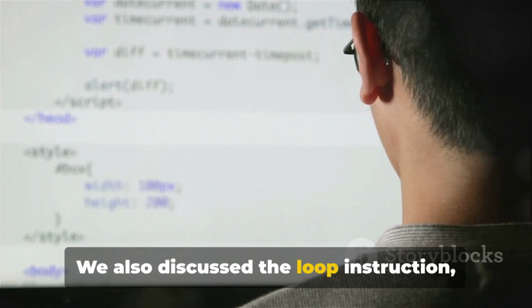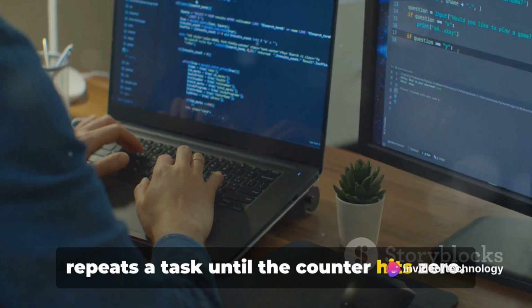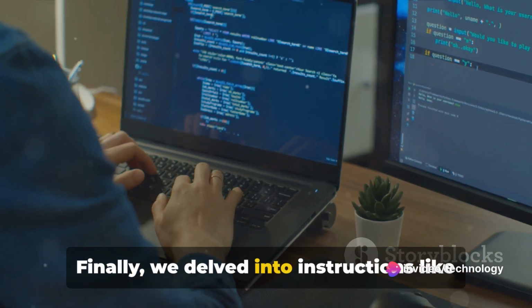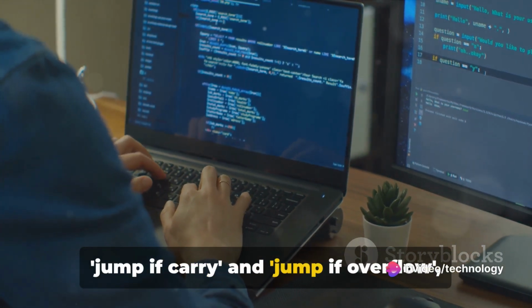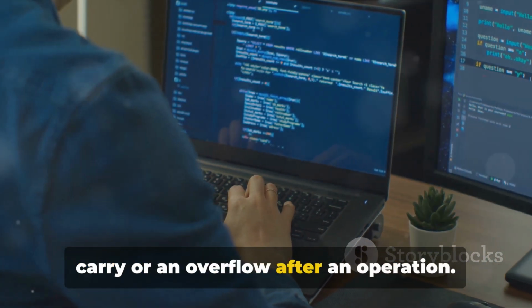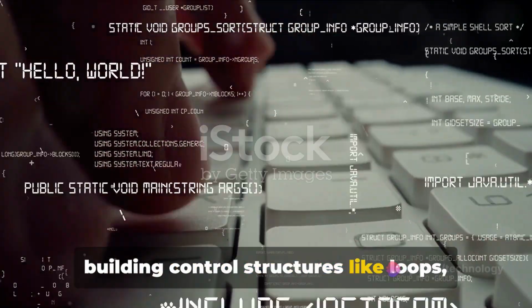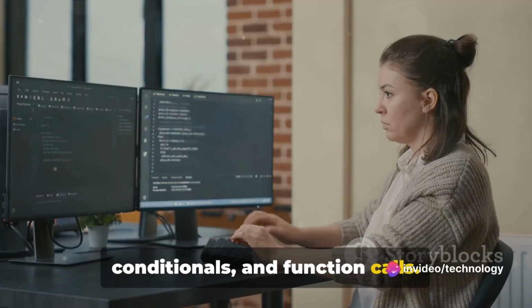We also discussed the loop instruction, which decrements a loop counter and repeats a task until the counter hits 0. Finally, we delved into instructions like jump if carry and jump if overflow, which jump based on the occurrence of a carry or an overflow after an operation. These instructions are foundational for building control structures like loops, conditionals, and function calls.